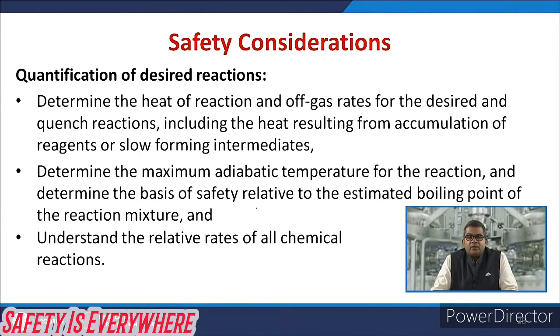Sometimes you need to determine the maximum adiabatic temperature for the reaction and determine the basis of safety relative to the estimated boiling point of the reaction mixture, and understand the relative rate of all chemical reactions, and sometimes this is inclusive of all kinds of side, unwanted reactions and major reactions, etc. Then you need to go for the quantification of adverse reaction. In this way you need to assess the thermal stability of a reaction mixture over a wide temperature range.